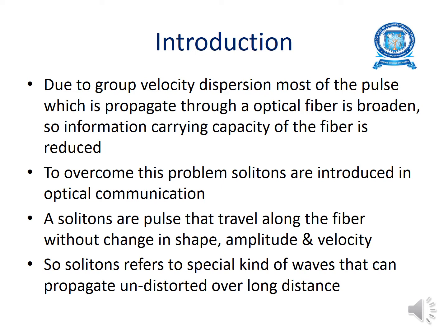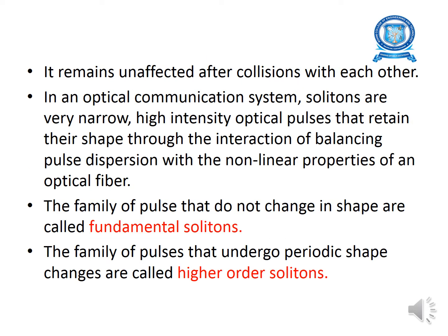The term solitons refers to a special kind of waves that can propagate undistorted over long distances and remain unaffected after collision with each other. Solitons take advantage of nonlinear effects in silica, particularly self-phase modulation resulting from Kerr nonlinearities, to overcome the pulse broadening effects of group velocity dispersion.